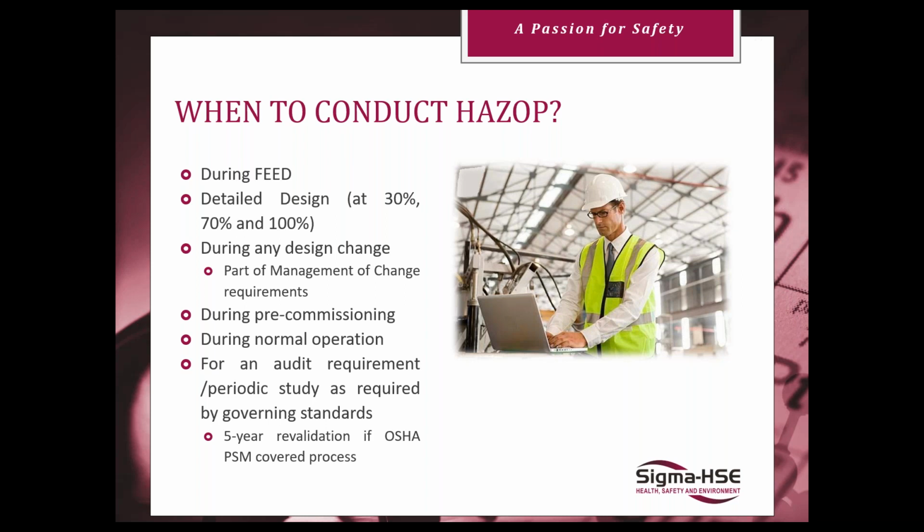Anytime you're making a design change, once you've finalized a design, if you have a management of change process, if you're making anything greater than a like for like, you should at least look at it and see if there are new risks. And if it's a major change, you may want to update your HAZOP there.